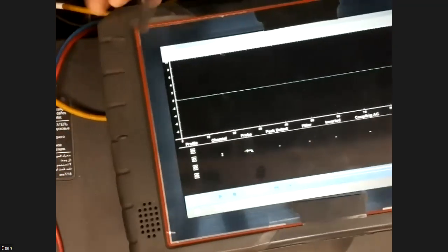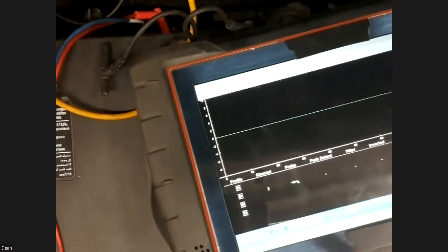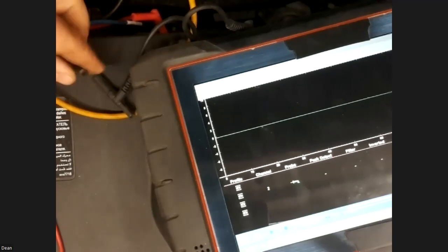This is important information. This is a stackable lead. So instead of getting a voltage spike, say from a secondary ignition system or whatever, through this line, it's going to go directly to ground. It won't go through the module. Very important.